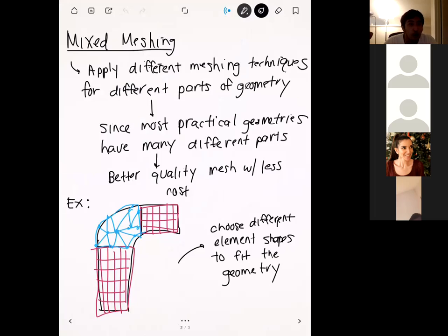When you choose a hex dominant mesh in Ansys, Ansys will try its best, based on what it can see from the geometry, to choose areas where it thinks tetrahedrons would look better. But it's not perfect, unfortunately. Ansys is looking at features of your CAD model, like where the curvature is highest, or what the radius of curvature is in these areas. It does a pretty decent job for most simple cases, but for some cases it's just going to flat out fail.